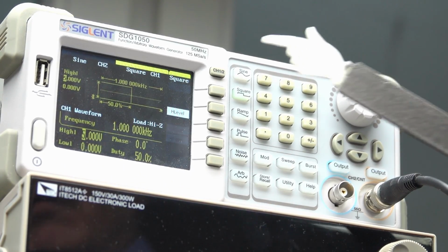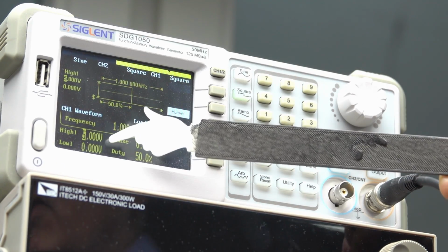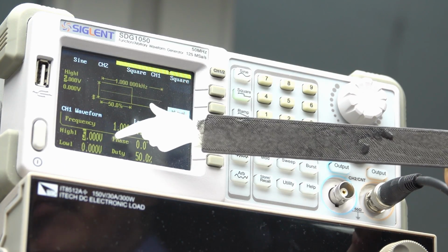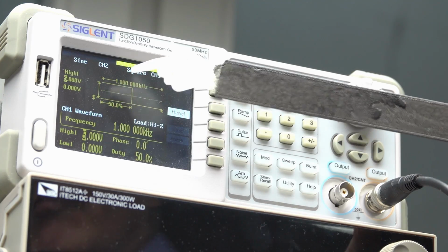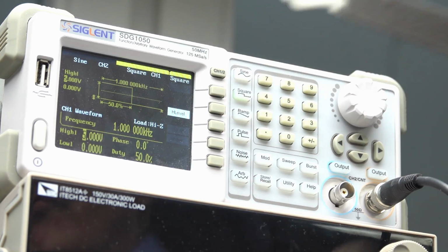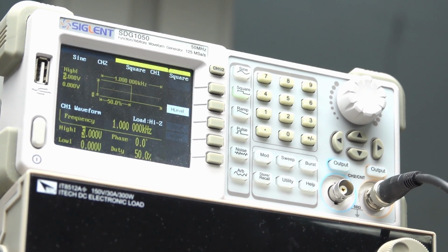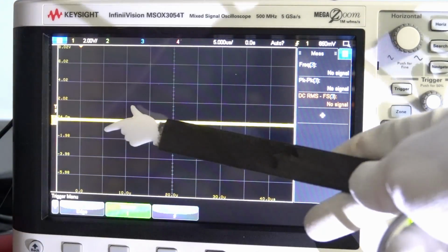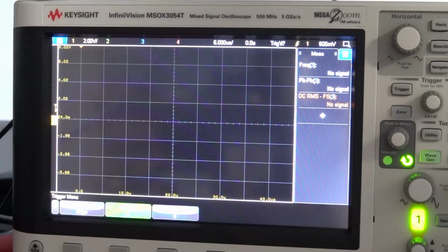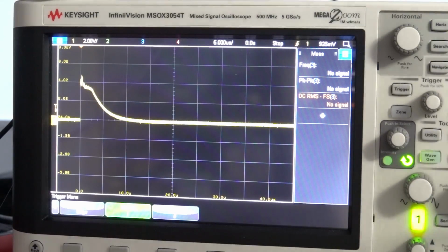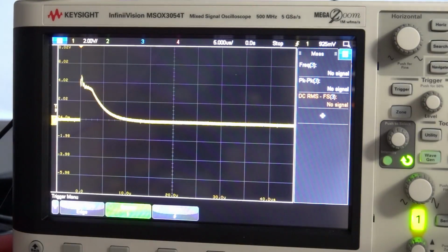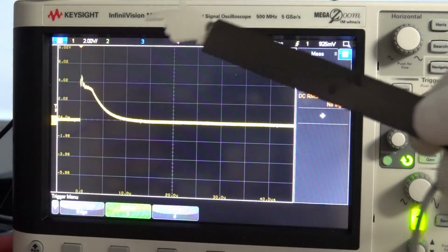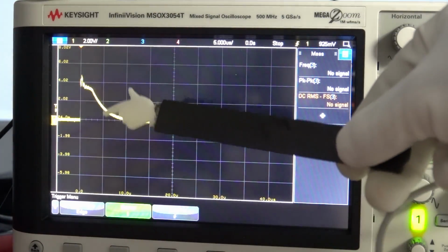Because I need higher frequencies for that test, I replace the Arduino with a signal generator. It creates the same pattern of 0 and 5 volts with a frequency of 0.5 Hz. The oscilloscope shows nothing. At least nothing visible. Only if we trigger it to a positive or negative signal and zoom in, we see the very short spikes which resemble a discharging curve of a capacitor.